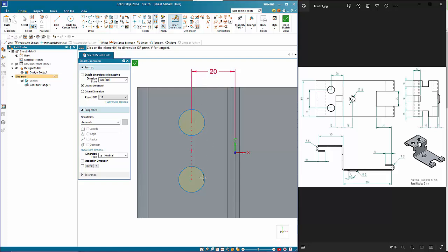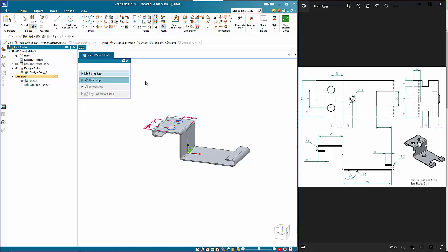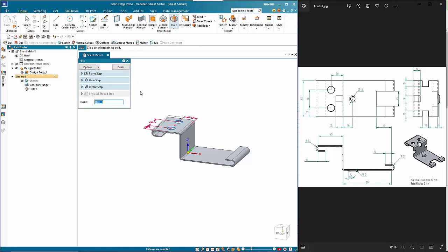And then this is 15mm down from that edge, and then 30 on there. So we can close this command, and that is going to be a through next, just to make sure. We'll go downwards and right mouse click to finish.